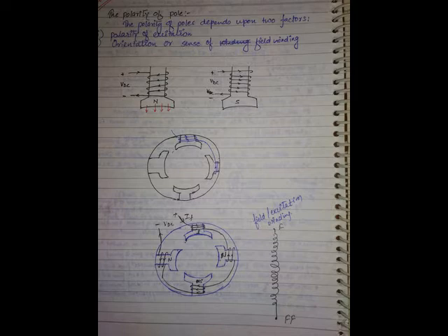Means the armature core material should contain superior magnetic properties. You have written under yoke good magnetic material, but under armature core you have to write superior magnetic material. Why? Because all the work is done in the armature only. The yoke is just to allow flux to flow through it. So when compared to yoke, the armature core should contain superior magnetic properties, that is high permeability. Right?